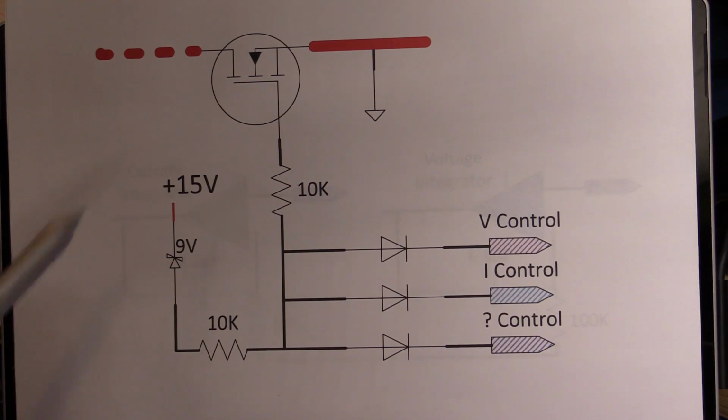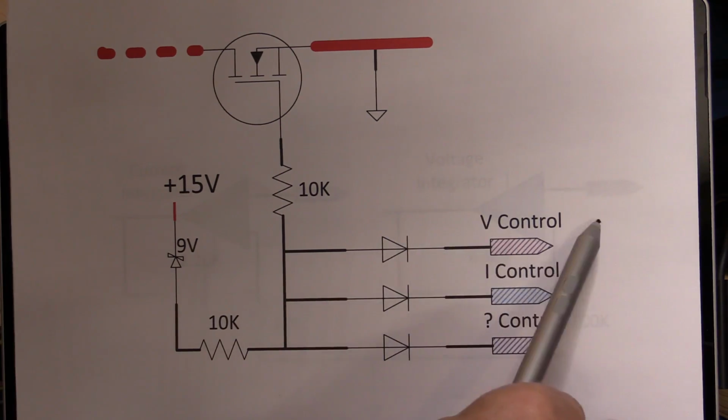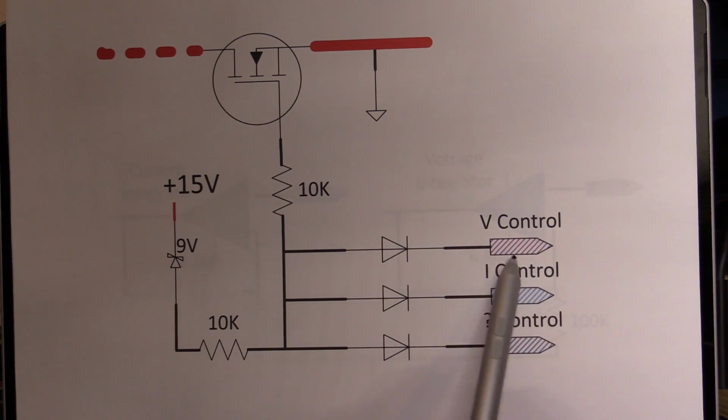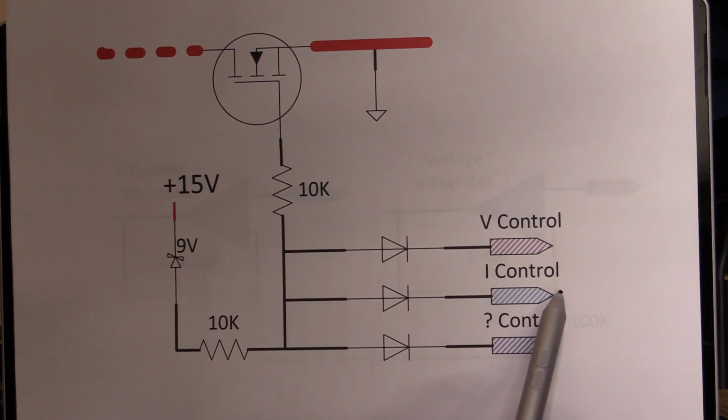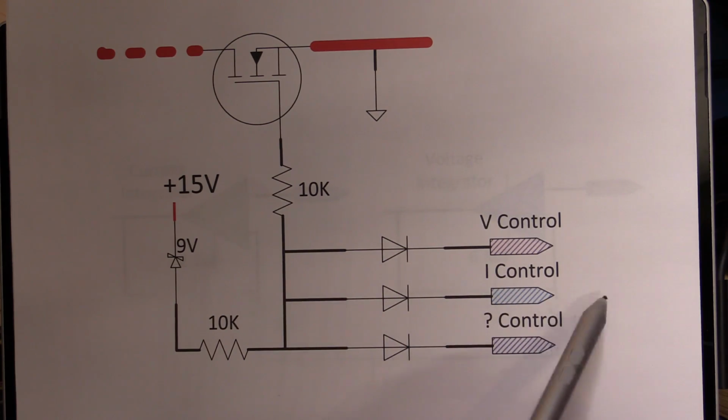Because you want to have a voltage control and a current control, say you've set 25 volts for your voltage limit, and you've set your current to be 3 amps, but your load is only drawing, say, 2 amps. Then your current control is going to start driving higher because it says, oh, I'm not actually balanced on my current. I want to increase the drive so that I can get to my current and balance my op amp.